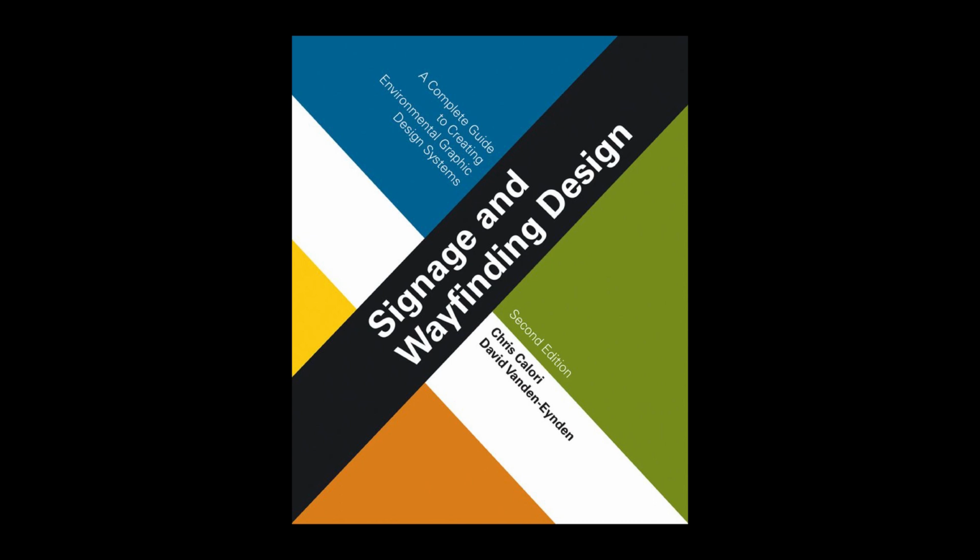Invitation to bid. The invitation to bid provides specific information to bidders on preparing and submitting their bids. This information can include when and where a pre-bid conference is held and whether attendance is mandatory, when and where to submit bids, contact information for the contract representative, brief scope of work, bid guarantee period, work completion dates, and any other information that may be pertinent to bidding the project.